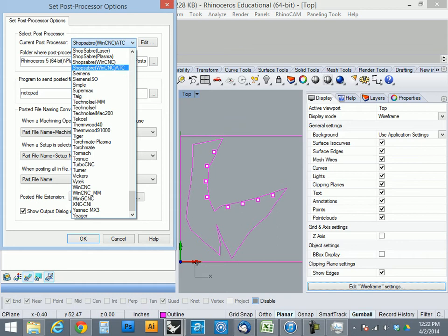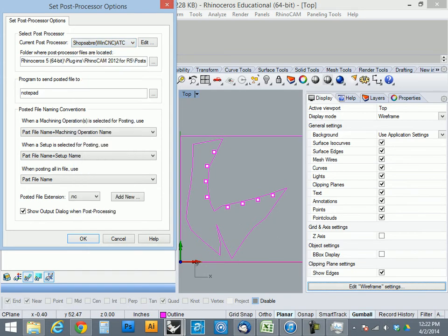So for those of you that were authorized in M&M, that's a different machine. We're using this machine. It's actually on the list. So that's the one that's in the Idea Shop. This is critical so that the NC file that's generated is specific for the machine, because with the G code, certain machines have different commands, like tool changes and so forth. So we have to make sure that's the first thing we change.